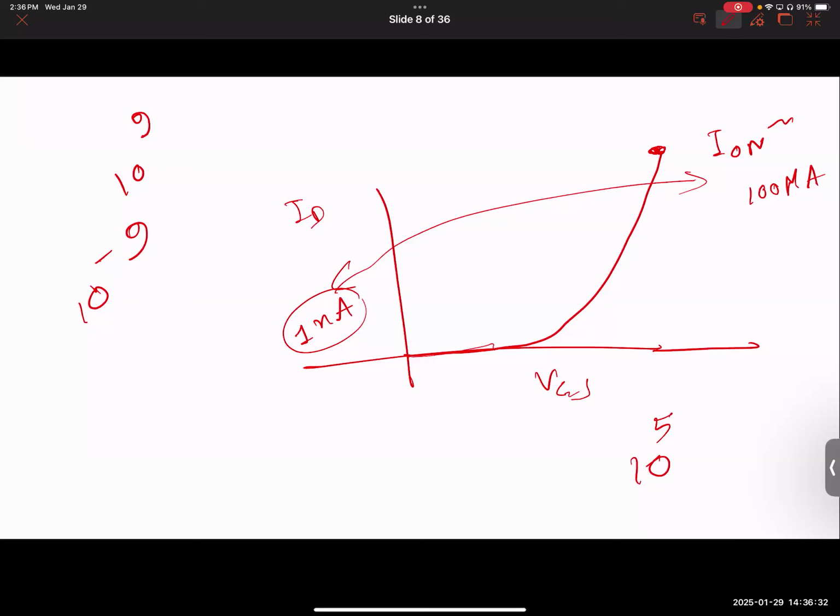So every one of those transistors is leaking 1 nanoampere, even when there is no VGS. I haven't even turned on the transistor, it's off. But there will be a current. What is that current? 1 nanoampere. How many do you have? A gigabyte is nothing now, right?